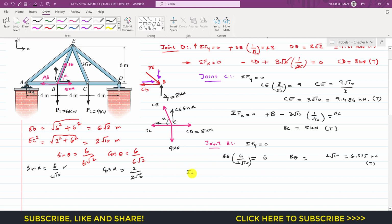Similarly, if we apply the summation of forces along x equals 0 at joint B, AB is acting in the negative x direction, so I will write minus AB plus the cos component of BE, so I will write BE, and BE is 2 square root 10 cos of alpha, and plus that 5 kilonewton force, that BC member force, so I will write plus 5, and this is equal to 0. If I bring this AB to the other side, it will become positive, so we will have the equation like this, and cos of alpha is this thing.